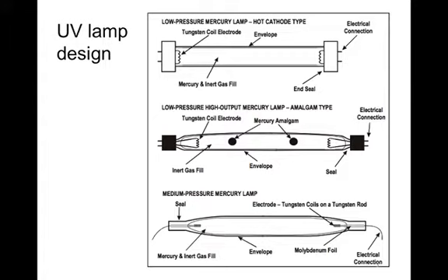The way that UV disinfection works in treatment plants is that we generate these UV wavelengths that are very potent at causing disinfection, and we generate them with lamps. The most common lamp design is the one shown at the top. This is a low pressure mercury lamp. It's a long tube filled with mercury and an inert gas, and there are electrodes at each end that produce an electrical discharge, and the electrons in the mercury atoms get excited, and when they relax, they release photons.